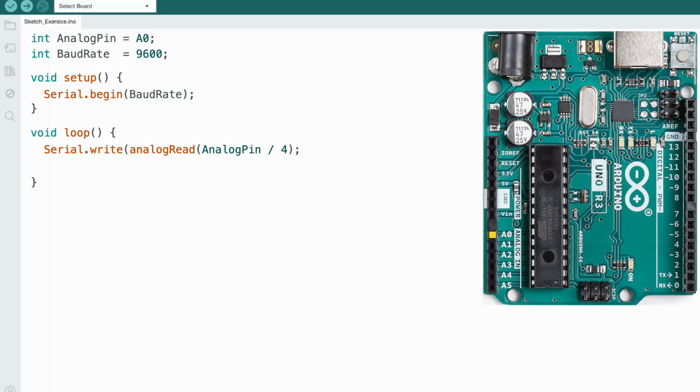That's all that we're doing. We're just writing to serial as opposed to doing a println, because we're not going to be running the next portion of this project from our Arduino IDE. We're actually going to be running it from our Processing IDE, and so doing a Serial.println kind of falls on deaf ears, if you will. Instead, we need to actually write to the serial.